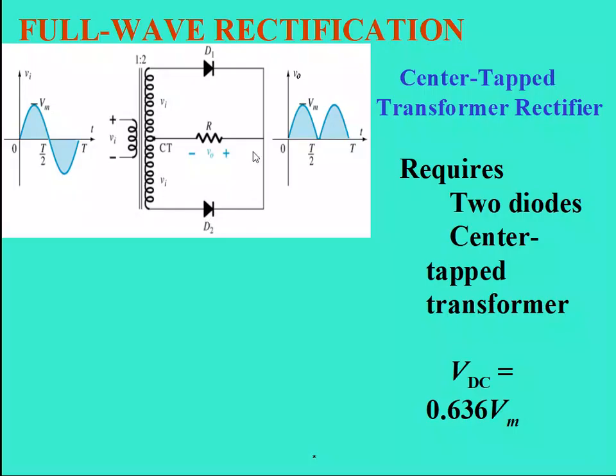And you can see the RL, the combination of the circuits is very important. Here, when D1 is on, then this part is active. When D2 is on, then this part is active. So ultimately D1 and D2 both are active in this case, and we will always get the output across the load resistance. The desired output will be like this. So here the negative half cycle is basically inverted, and that's why it is coming up.